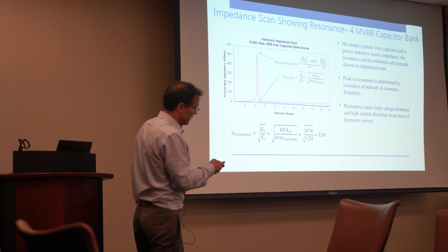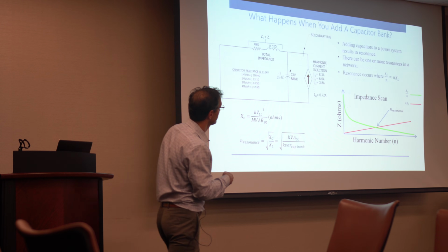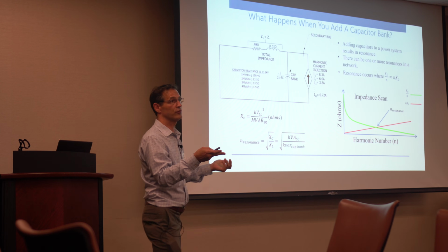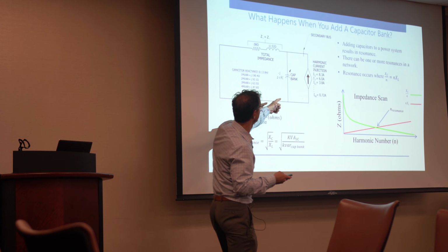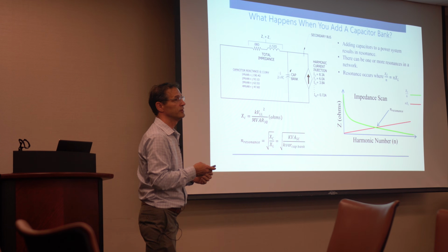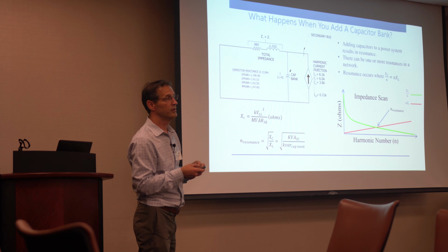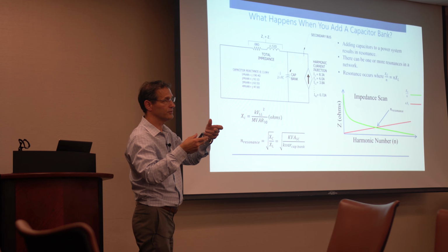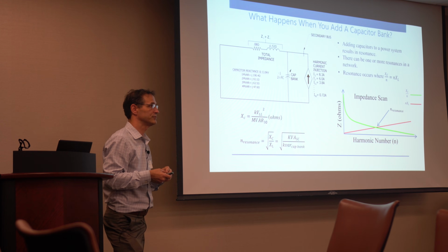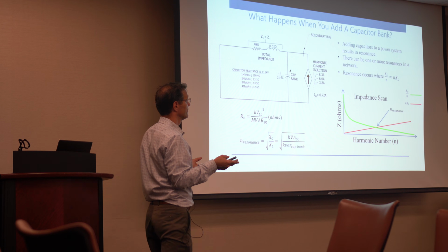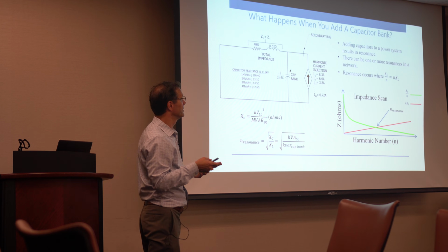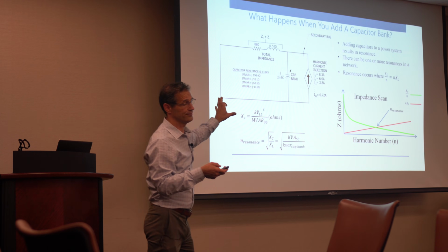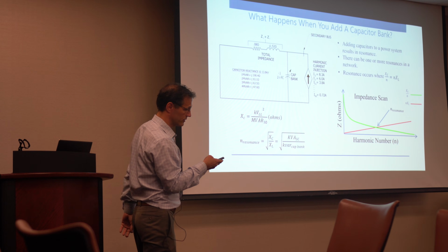So if I were to go back to the slide, and if I were to look into the network from there and calculate the impedance, it's the power over sum, right? That's the rule. It's a parallel circuit. You got this in parallel with that. So it's a power over sum rule that you can apply. You have to make sure that it's a complex quantity, so you have to take care that you have a complex number. It's not 100% straightforward, but this can be done very easily in Excel if you take a little time, and I've done this in Excel too.